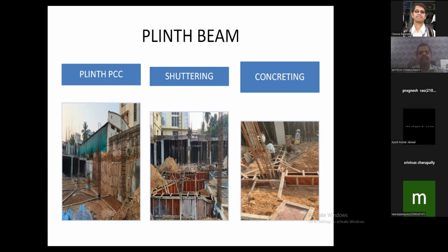Here, the engineer has to inspect clearly the main or the tensile bars. In many site conditions, the bar benders make a mistake with the extra bars or the tensile bars. What we are saying is that people will place them the wrong way. So our duty, the civil engineer's or the site engineer's duty, is to place the steel correctly.